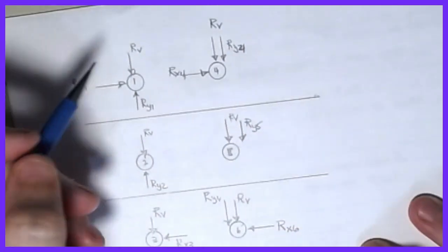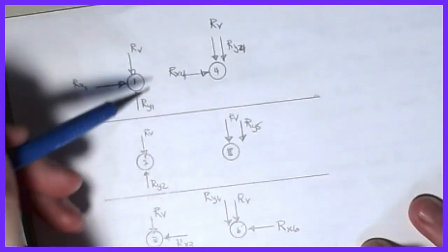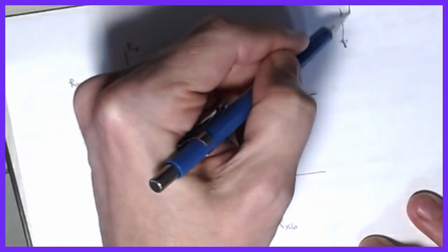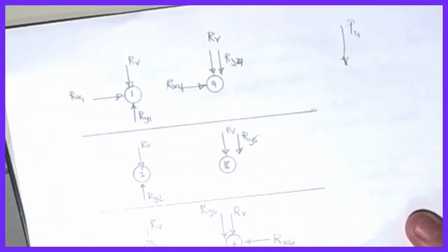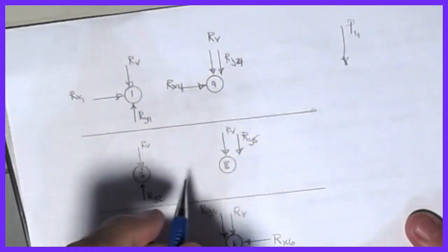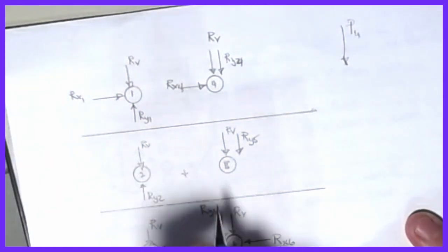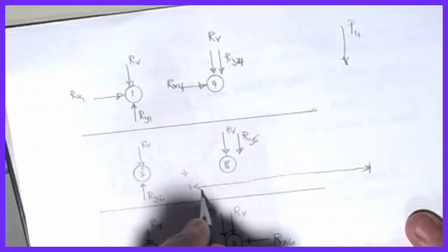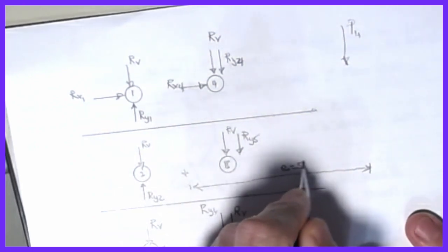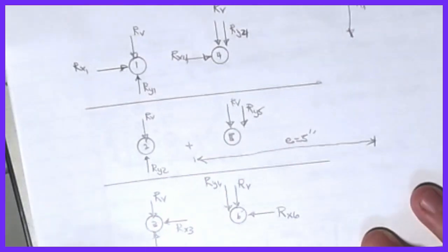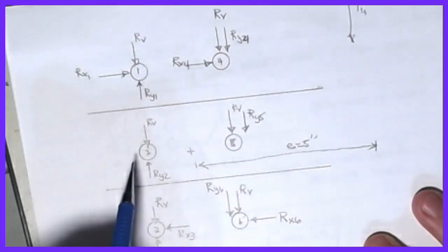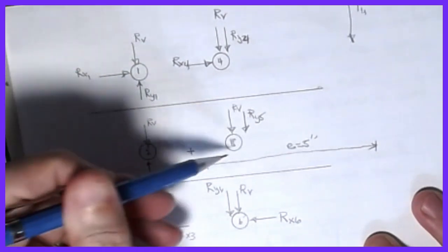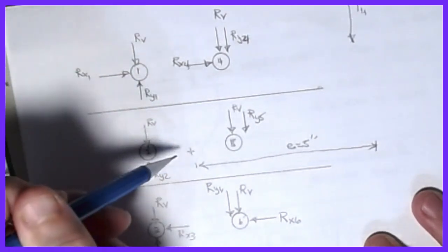Okay, and so these were the cases that we were seeing, and this is what it looks like as we're starting to combine things for a load that was out here somewhere, a PU kind of thing, at some eccentricity from the center of the pattern. All right, so again, this distance we said was an E of 5 inches. Okay, and so for that particular eccentricity, if you plug in the equations, you will see that this set of bolts actually has no horizontal force.